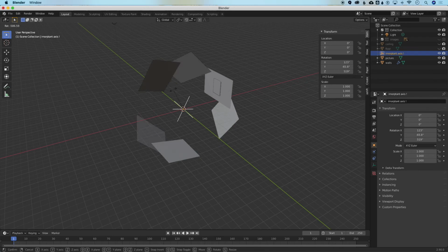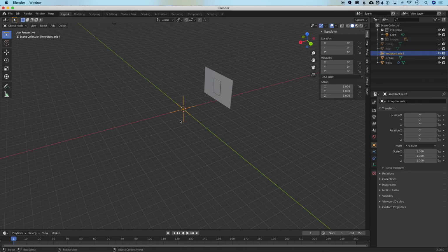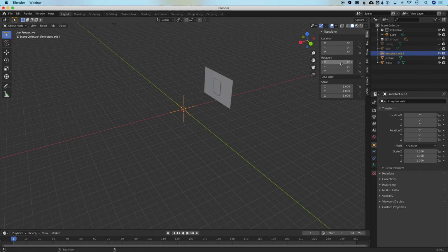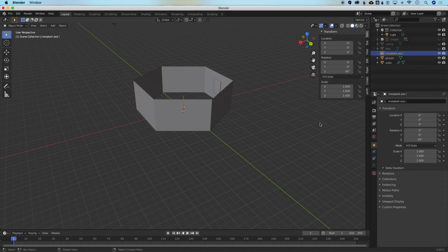This is quite beautiful and hypnotic to look at. I'm getting lost in it as we speak, but obviously not that useful because we want to remake a hexagon. So rather than fooling around with trying to eyeball the rotation, what I'm going to do is go to this menu here, and here where the rotation is set, I'm going to click on Z, and I'm going to type 360 because there's 360 degrees in a circle, slash for divide, and 6 because I have 6 sides. And now when I click out of that, we have our hexagon.